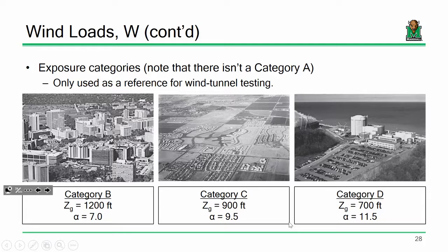That's a good question. So what do you do if you're in excess of this? That's when you start doing things that are a whole heck of a lot more refined. It wouldn't be off the wall to do something like a wind tunnel test: build a scale model of the structure and actually put it in a wind tunnel and start recording the response. That's pretty common for your really complicated structures. That's one way of going about it. Another way is to do some more refined computer modeling and things like that. Sound good? Okay.